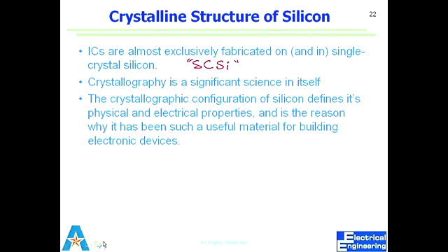Do we have wafers of it, or is this something we use for deposition? We deposit it. I see. We always deposit. They come deposited as well. But essentially, we don't get a wafer made of polysilicon. We always put it on. So can the structure of the grain boundaries be controlled? We do control them. Yes, sir.